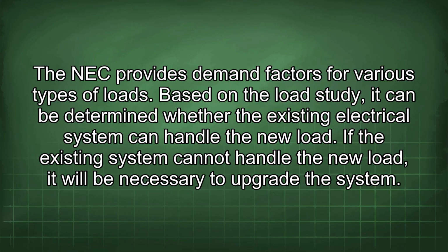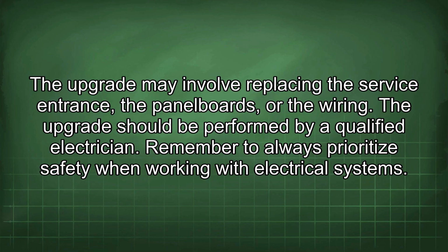Based on the load study, it can be determined whether the existing electrical system can handle the new load. If the existing system cannot handle the new load, it will be necessary to upgrade the system. The upgrade may involve replacing the service entrance, the panel boards, or the wiring. The upgrade should be performed by a qualified electrician.